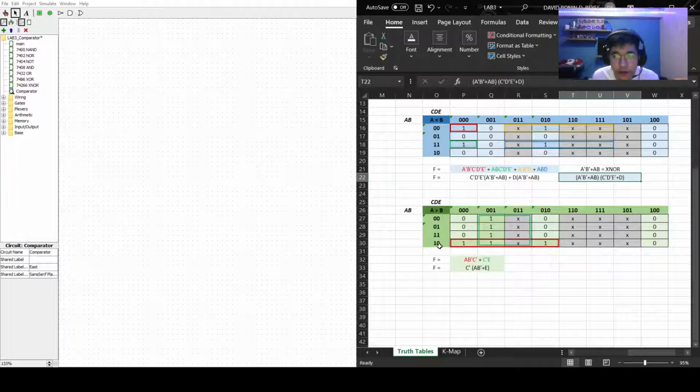Since it is covering only our last row, we could say that it automatically inputs 1 and 0, so A and B prime. Now comparing the four numbers above that is being covered by the red group, we could see that 0, 0, 0, and 0 for CDE is constant, so we put C prime.